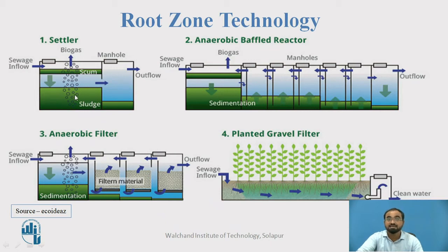It is acting as a septic tank. The effluent is taken out, and whatever supernatant is present is again taken out and shifted to the second chamber, or the second compartment, and whatever sludge has settled at the bottom is taken out and disposed of.